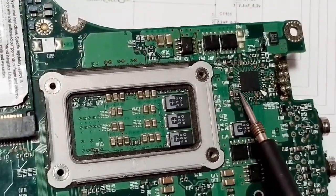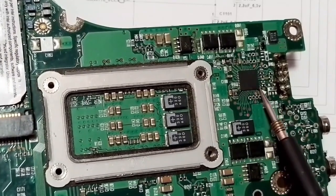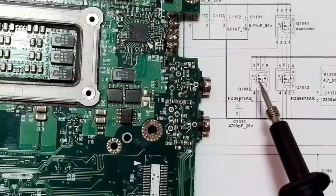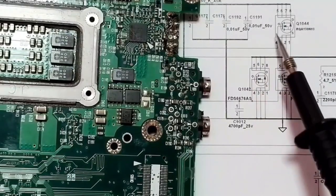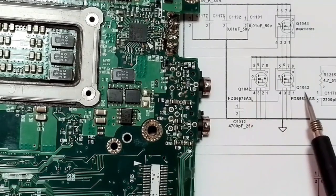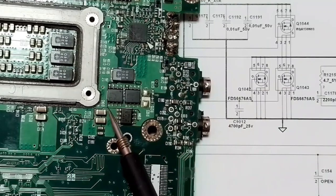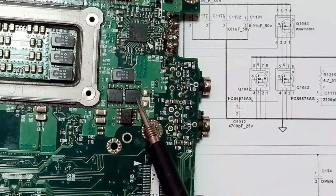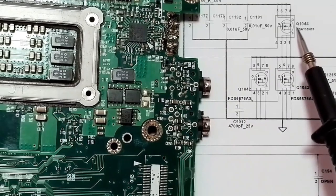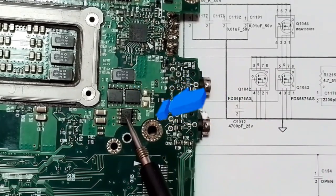U1018. So let's see in the motherboard, in the back of the CPU, as you can see, we have U1018. This is the CPU control IC. Then we have here 3 MOSFETs: Q1042, Q1043, as you can see. Here we have Q1043, and this is Q1042. And here, as you can see, we have Q1044.